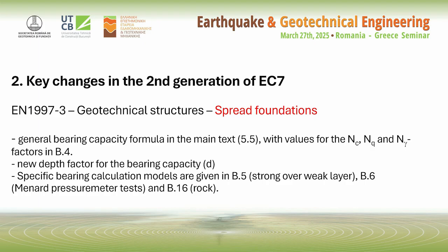What are the new things? A little bit, not many new things, but we have the general bearing capacity formula in the main text with the values for the bearing capacity coefficients. There is a new depth factor, which is called D, and in the appendix you can find specific calculation models for some cases, as for example, strong over weak layer, Menard pressuremeter test, or for rock ground.